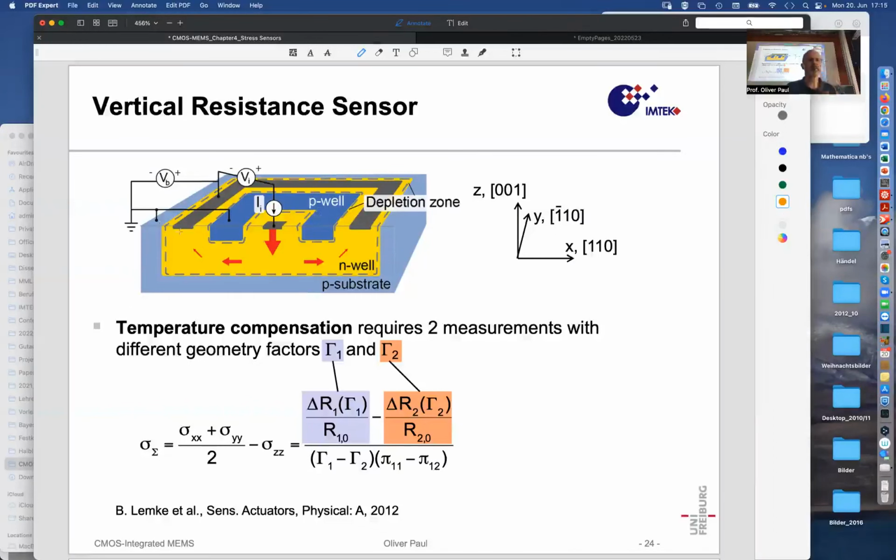I can hook them up and then bias them with respect to the inner conduction region. And of course, that has an effect on the width of the depletion layer between P and N. Varying this VB will make the depletion layer out here larger or smaller, depending on whether you're going more in reverse or more in forward direction, and the same here.